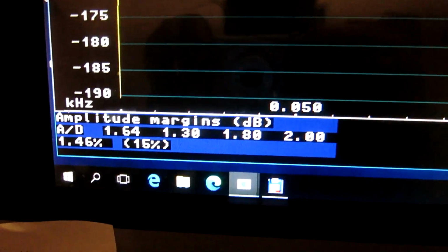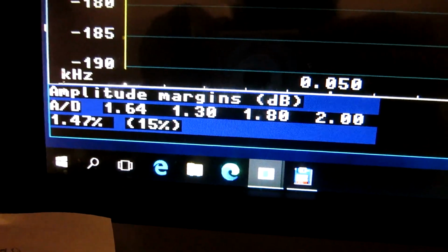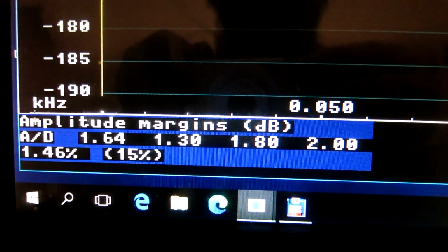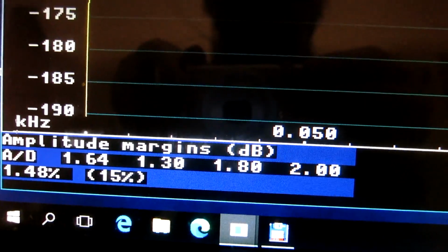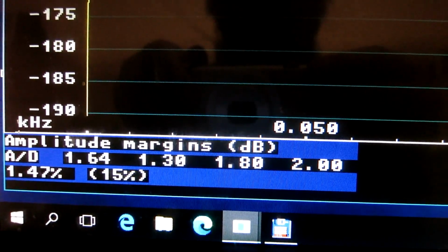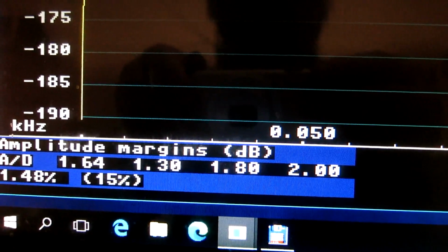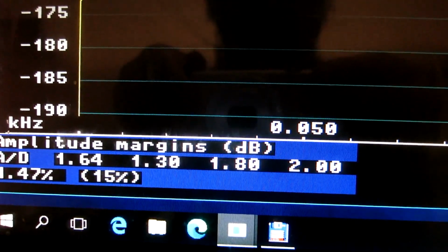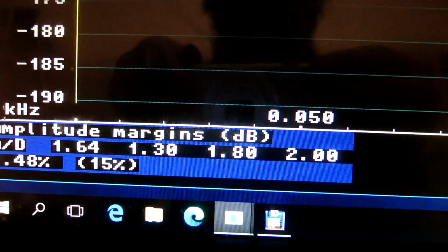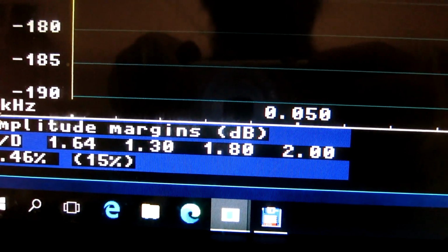I have added a second amplitude limiter. The level is only reduced by a couple of tenths of a dB, but the function that is doing the limiting is now considerably sharper. And I am looking whether this makes some difference in the amplitude noise.